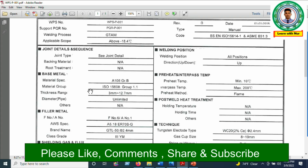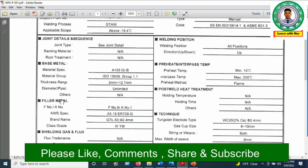If the thickness is over or under this, we cannot use this WPS. Then diameter of pipe is unlimited, so any diameter of pipe can use this WPS. Others here are not applicable.